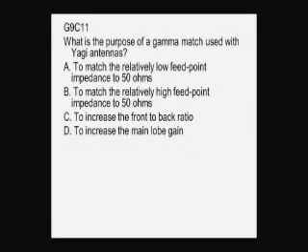What's the purpose of a gamma match used with Yagi antennas? The purpose of it is to match. Well, here you have gamma match, right? You got the word match right there, okay? So you have two answers here that have match in them. One of them happens to be correct. So throw these others out. And it's to match the relatively low feed point impedance to 50 ohms.